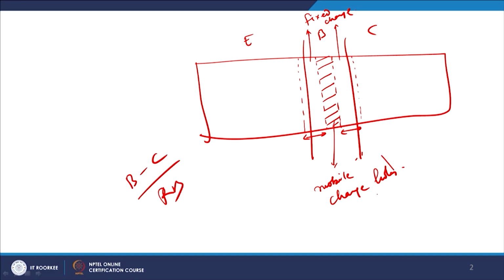So when you reverse bias it, that means if this is NPN, let us suppose, if you reverse bias it, then this will be something like this, right. Once you reverse bias it, this depletion thickness will further increase, as we had discussed earlier. That means reverse bias will increase the depletion thickness. So the effective depletion thickness increases this side. So what happens to the effective base width?